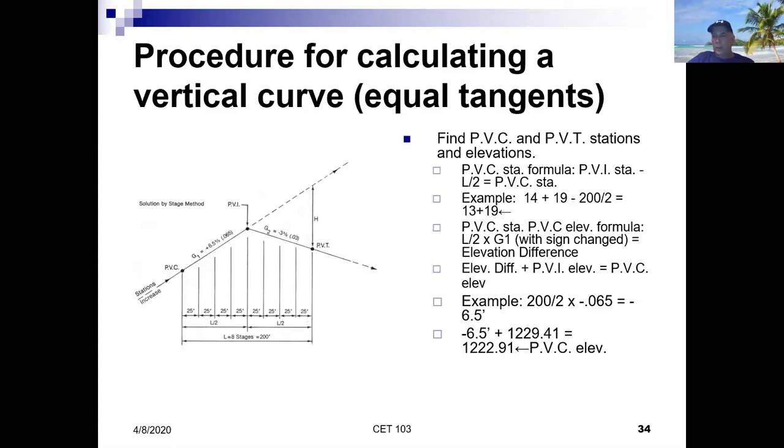Again, just to recap, what we did learn along the way was we talked about the importance of the vertical curve. We talked about some of the important elements of a vertical curve, which is the point of vertical curvature, or the PVC, the PVI, the PVT. We also talked the key elements about the grade going in and the grade going out. We also talked about two very important types of vertical curves, which is the, excuse me, I'm going to go back to a slide.